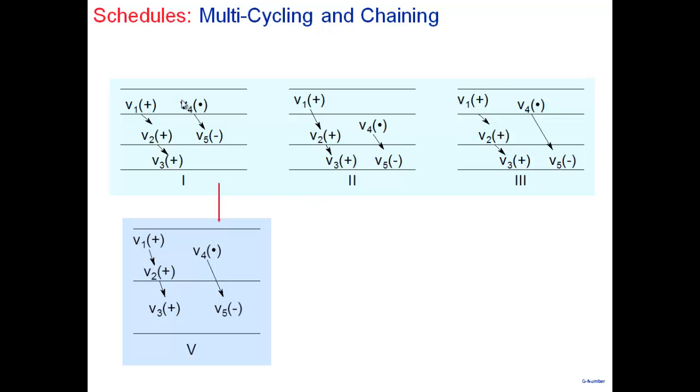Earlier, remember, the earlier picture was that each one required 1 adder, 1 subtractor, and 1 multiplier. And my clock period was determined by the multiplication time. Now let's look at this one. Does it require more resources? How many adders, subtractors and multipliers? I require 2 adders and a multiplier. I require an adder and a subtractor.